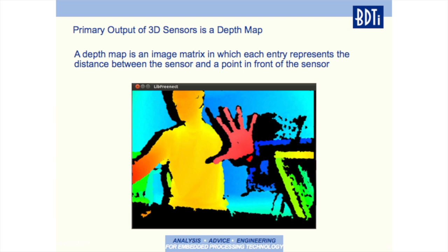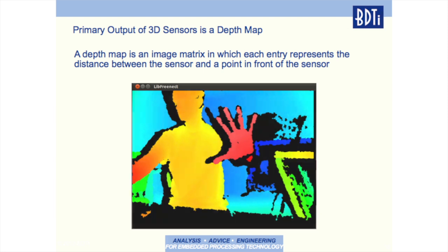Now, in a traditional 2D image, like the kind generated by the CMOS or CCD camera sensors that Eric just described, each pixel's intensity is mapped to the amount of light that it actually measured, versus a 3D sensor where each pixel is proportional to the depth from the object to the sensor. In this image, it's been color-coded such that the red pixels are closer to the sensor, and as you move progressively further back, it's yellow until it's blue, the background.